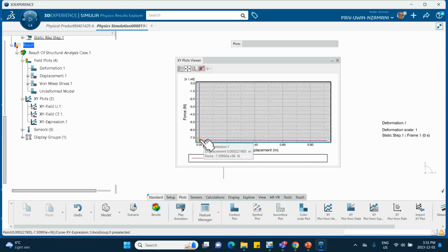So there's buckling here, and then there's a sideways deflection. Now, he makes a very good point. He says, well, look, if you want to get this 7.4, why did you have to do all of this? I could have done an eigenvalue calculation and come up with a critical buckling load. The problem is that if you have any nonlinearity, that number that you get from linear buckling analysis will not match this number. So you have to be very careful and do nonlinear analysis. We were just kind of lucky here that although we did have some imperfections, it was close enough. So you got to be careful.